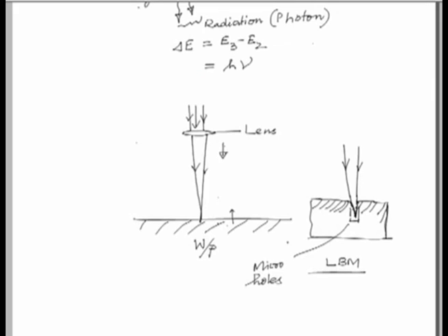like in this case, this area wherever we are machining. So, near to this area may get affected further, or we can say this zone on either side of the cut can be considered as the heat affected zone, where the property of the metal or the alloy can be different.